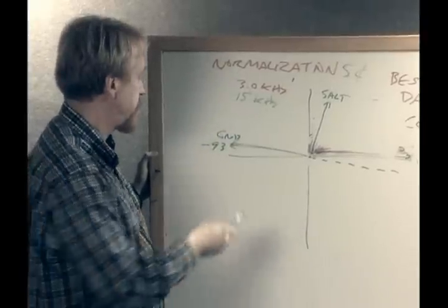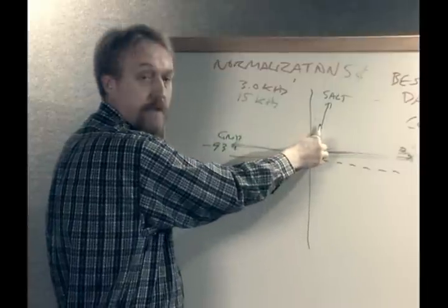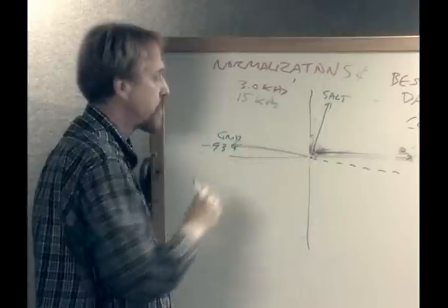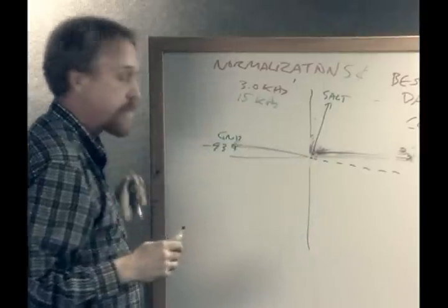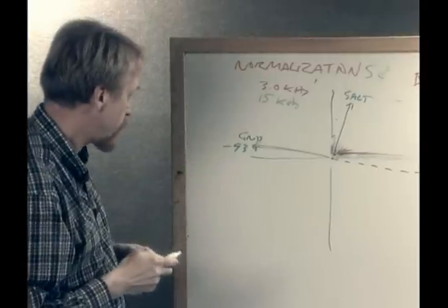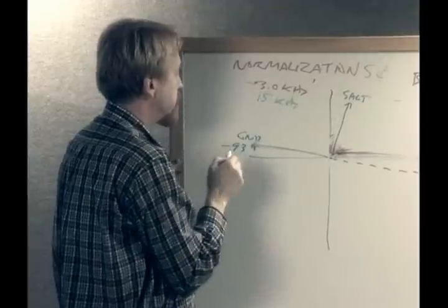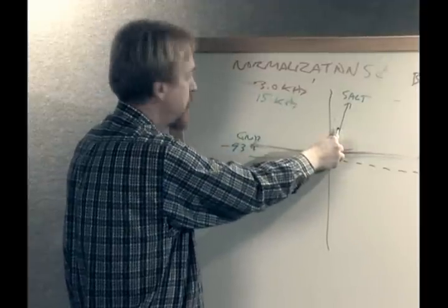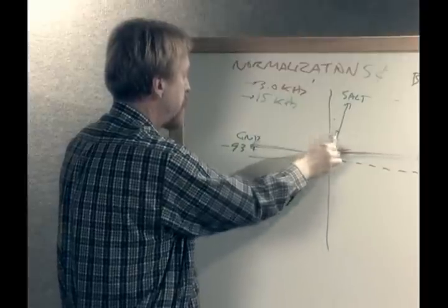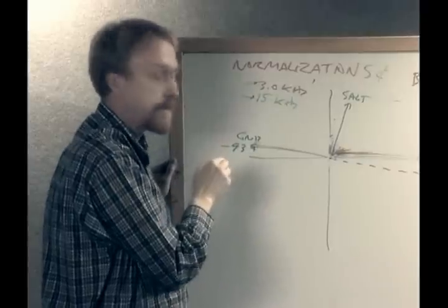So consequently, if you go to the beach and you balance your detector to the black sand, you're going to be very sensitive to the salt. If you balance to the salt, you're going to be very sensitive to the black sand. And the DFX has something very useful, which is a 2-frequency all-metal mode of operation. What we do there is we balance the 3 kilohertz signal to salt. We also balance the 15 kilohertz to salt. Now both of them are sensitive to normal ferrous ground or to black sand.